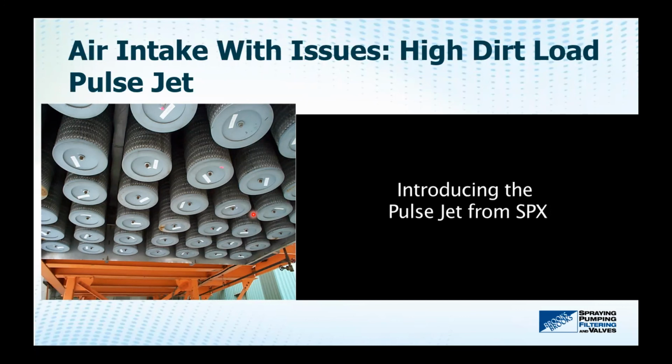And since they're self-cleaning, it also depends on how the cake builds on the media and what type of dirt it is. Because if the cake builds a nice layer on the surface of the media and doesn't actually penetrate the media, then it's easier to remove it, and the media will have a longer on-stream life before you hit a terminal pressure drop. Yeah. So when they size it, they take a look at the dust and size the filter so that the dirt or contaminant actually cakes on the surface of the media and doesn't penetrate the media and start to block up the pores.